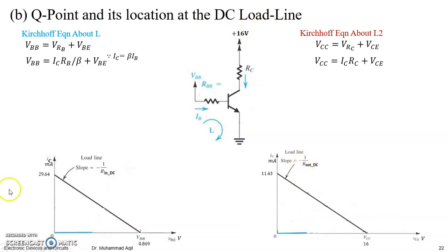So we have already drawn the load lines, and we have written the Kirchhoff's voltage equation on the input loop and on the output loop, right? So we will be requiring this, but no more hypothetical computation for x and y intercept to draw the load line, right? So now we have to find the solution of these two equations. Where is the VBE, where is the IC, where is the VCE for our available values of VCC and RC and so on, right?